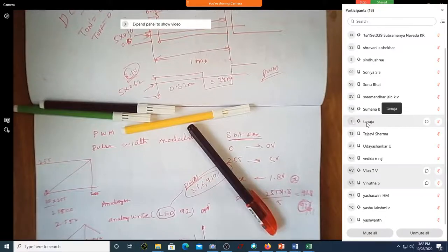In your Arduino, which is hardware connected outside, the serial monitor is on your screen. If your microcontroller has to communicate to the computer, you need to have some communication. That communication happens through the serial port, and there is some baud rate, some rate at which they need to communicate. So that's what serial dot begin 9600 is: the baud rate at which the microcontroller in your Arduino and the system CPU are going to communicate.